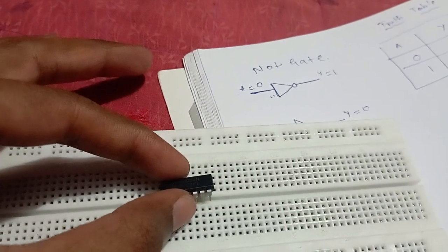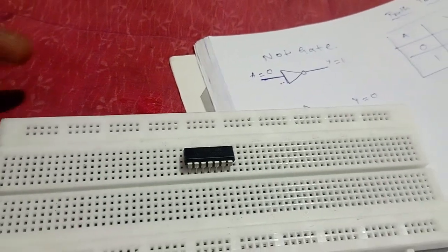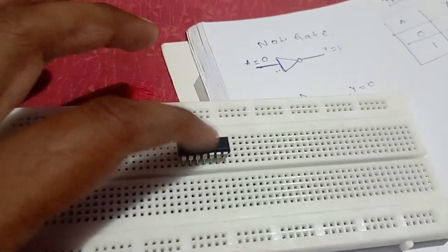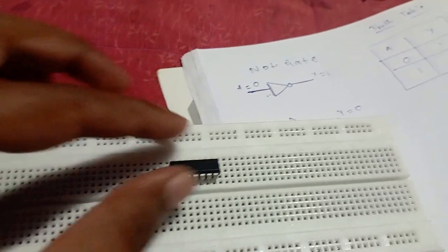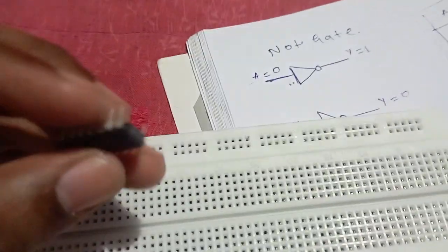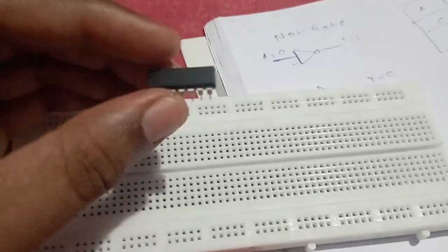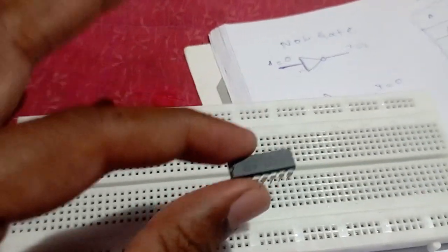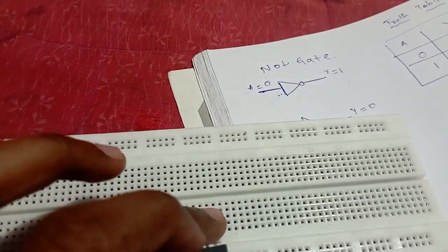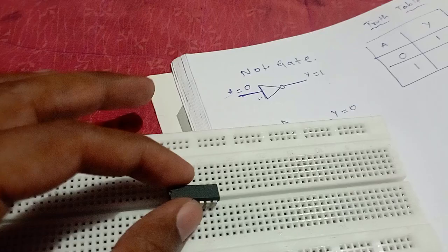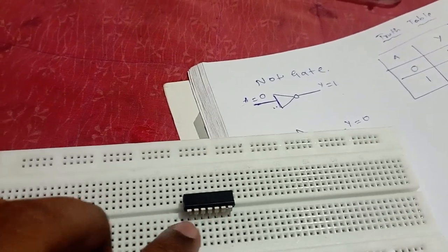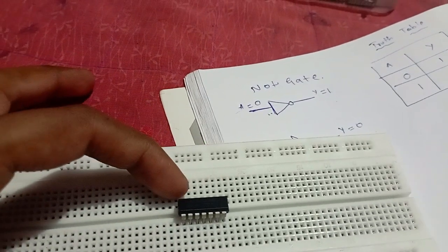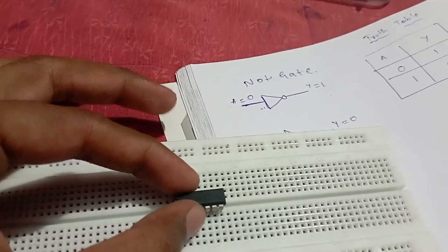If we connect the breadboard simply in this fashion, it is not going to work, because if I connect in this way, the same pin is going to be connected with this side pin, that is, they are going to be shorted, so the gate doesn't work in that way. So we have to connect the IC in such a way at this breakage, because there is no connection between this line and this line. If we connect this in this fashion, it is going to be separated, so that this pin is in another row and this pin is in another row.